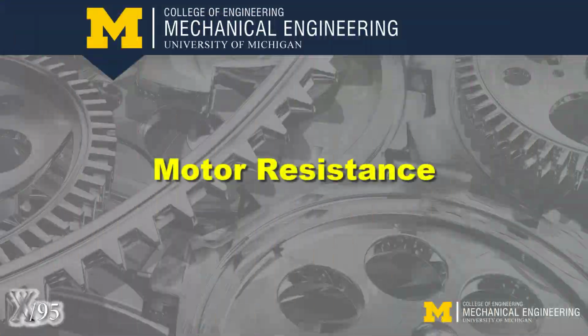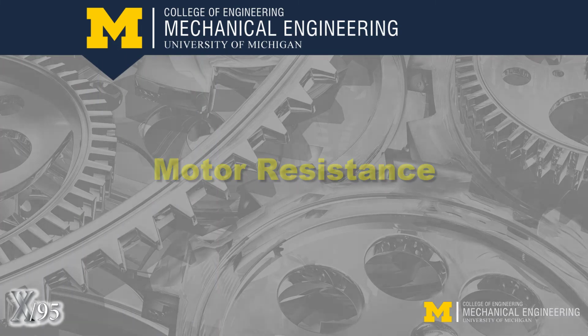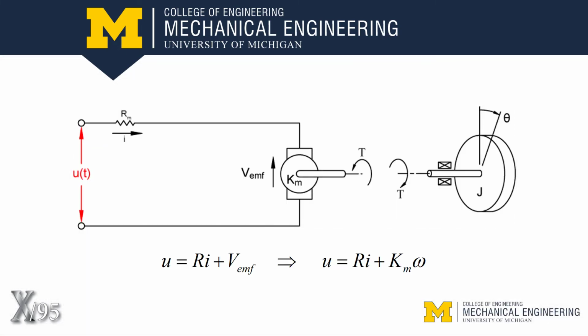The electrical resistance of the motor can be experimentally determined. Using the system model, sum the voltages in the circuit. Notice that if motor speed is held at 0, we can isolate the resistance.